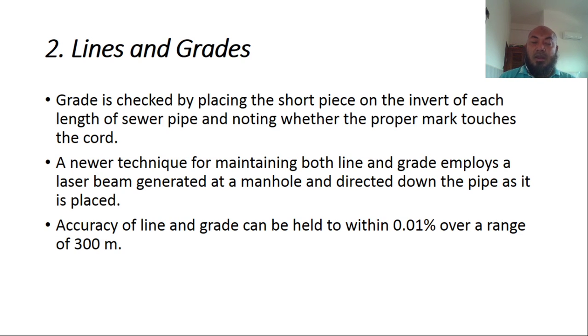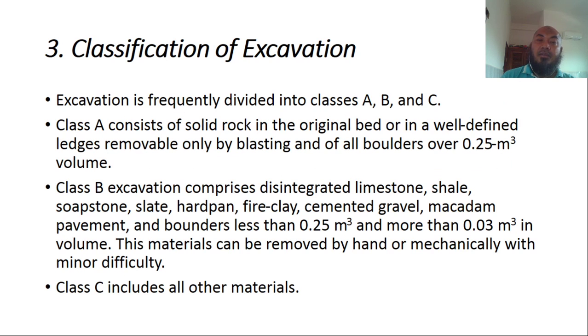But right now, line and grade is easily applied by using automatic leveling. We can use leveling to do the job, or we can use the theodolite, but mostly we use the leveling to get the elevation, and then apply the grade.